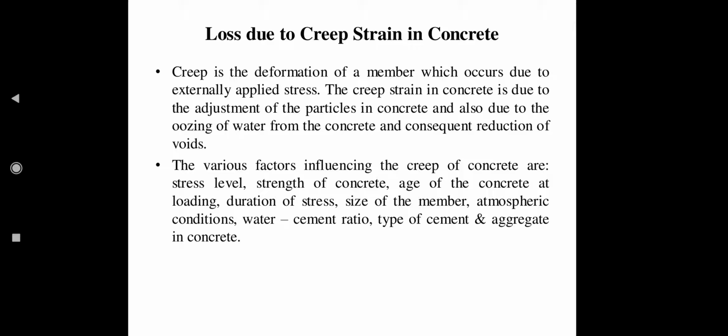So there are some factors which influence the creep of concrete. The factors are stress level, strength of concrete, age of concrete at loading, duration of stress, size of the member, atmospheric condition, water cement ratio, type of cement, and aggregates in concrete. So these are the factors influencing the loss of pre-stress due to creep of concrete.